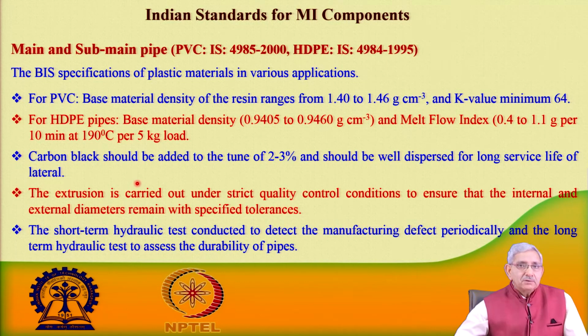Carbon black should be tested. Similarly, the extrusion is carried out under strict quality control condition to ensure that the internal and external diameters remain within the specified tolerance.